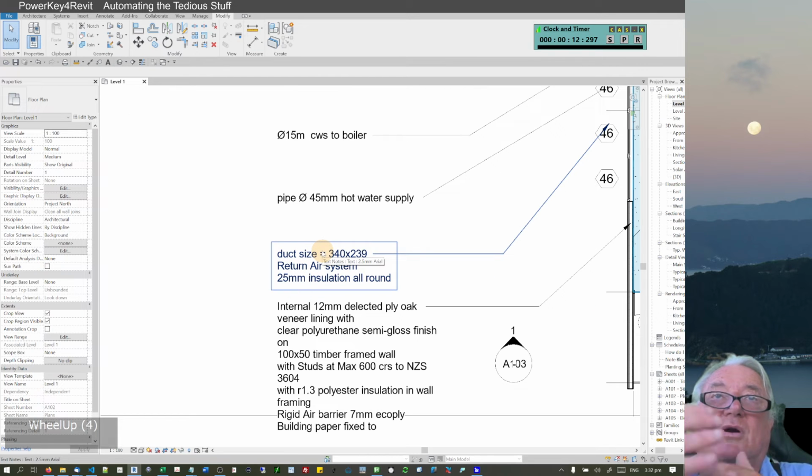A lot of the time you're talking with the duct and saying the duct size is this, is it got insulation, is it internal insulation or external insulation, and which system does it belong to? And then is it a flexible duct, or a round duct, or a rigid duct? So you can actually have a lot of those pull-downs.